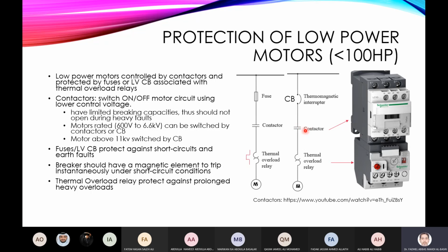Let's say a contactor is designed to be switched on 1 million times during its lifetime, while circuit breakers are not designed for such. Although a circuit breaker is used for switching on and off, as per design, circuit breakers are not designed for frequent switching. Okay, low voltage circuit breakers.